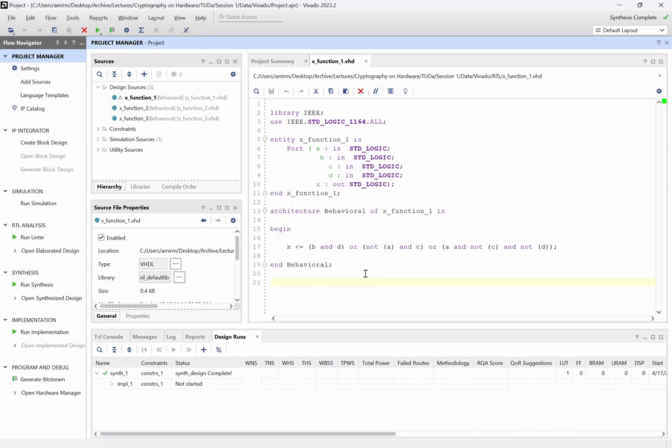Okay, what was the question? Just from experience from last semester, what are the hardware requirements for this program? Like memory, the amount of memory it takes? Vivado usually is a bit memory hungry, I have to say. The number of CPUs that you have doesn't make much difference. It doesn't use many CPUs, at least in the free license version. But you don't need a server for that, particularly for the assignments that we have for the lecture.